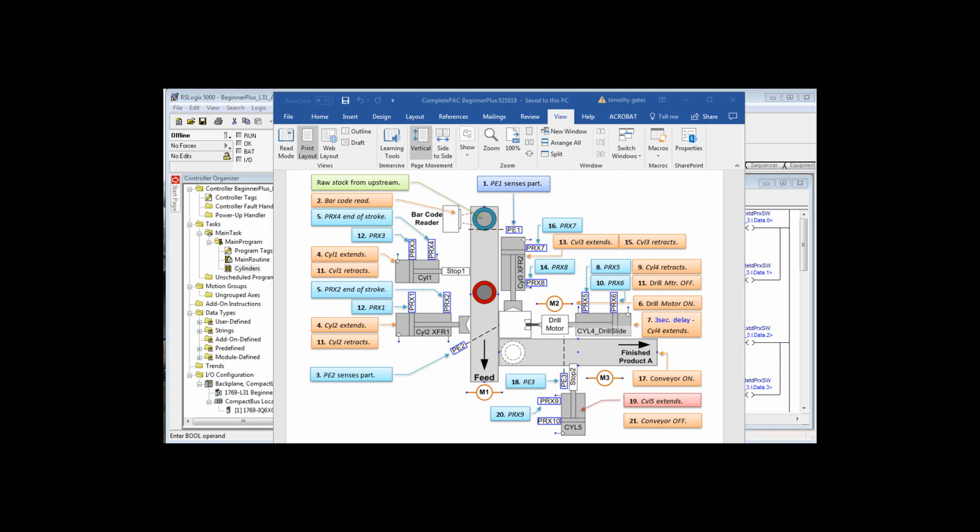They just go on when it's fully extended and fully retracted, or maybe it goes on before it's fully extended and retracted, and there's a little bit more motion there. In most cases, you want to add a little delay before you say it's actually extended or retracted, just to make sure it is, based on who installed these sensors on the cylinders and how they adjusted them. You'll see this out in the field.